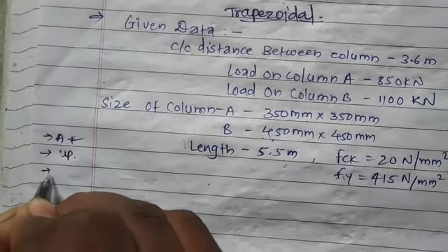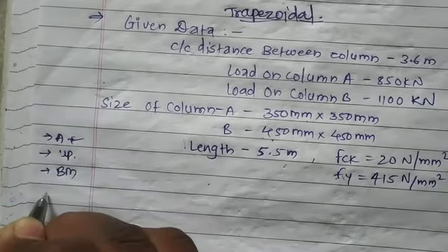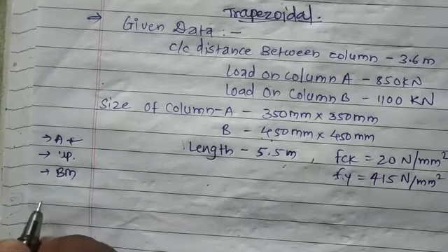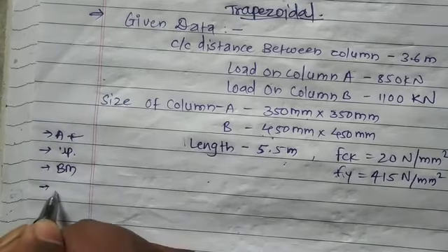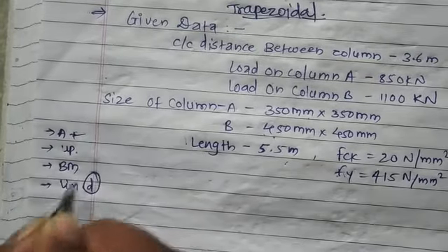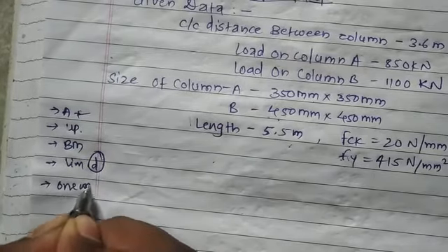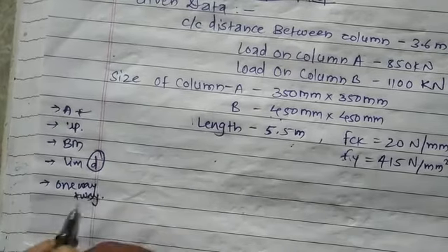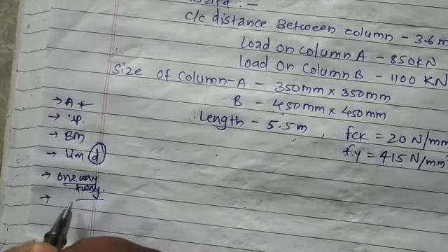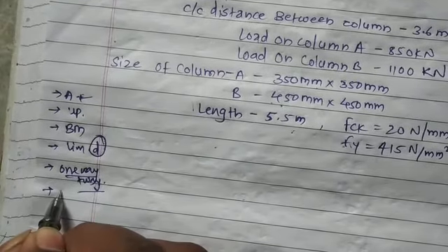After that, we'll determine the bending moment at various points in the footing, and by equating this bending moment with limiting moment, we'll calculate trial depth. After calculating trial depth, we'll check this trial depth for one way and two way shear at different positions. After getting the checks of one way shear and two way shear satisfied, we'll move towards the provision of reinforcement.